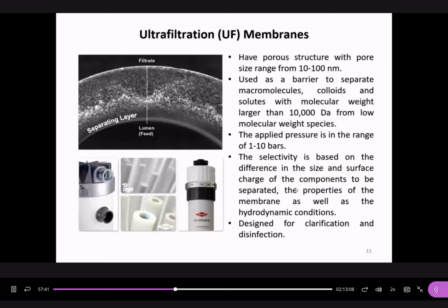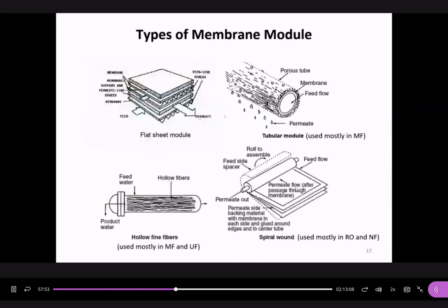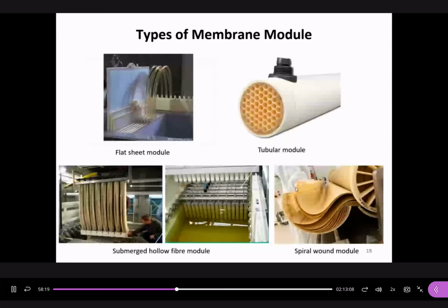Okay. And within this column, we have thousands of this type of hollow fibers, right? We could have this spiral wound, so we wrap membrane sheets around the permeate tube, right? And we could have this flat sheet module, or this tubular module. We have some photos here. Flat sheet module, tubular, hollow fiber membrane. The thousands of these fibers are arranged.